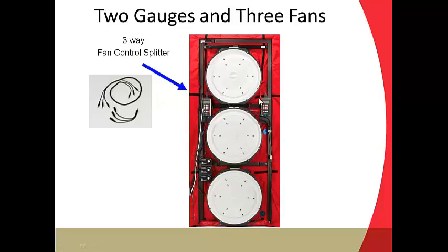And typically, when we're doing big building testing, we don't use the rings at all. We have a red nylon shower cap type thing to cap the fans rather than using the rings to cap the fans, and we just run all the fans wide open.